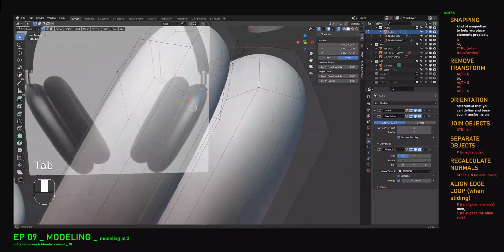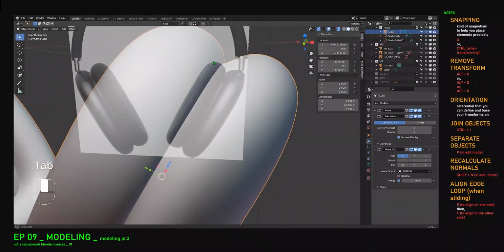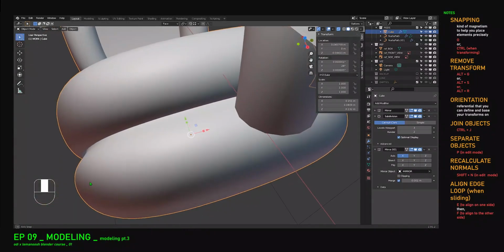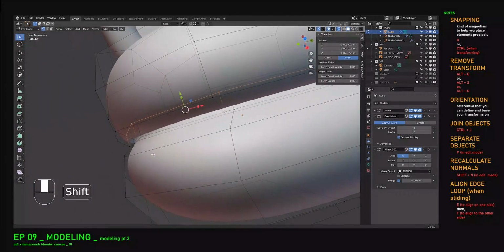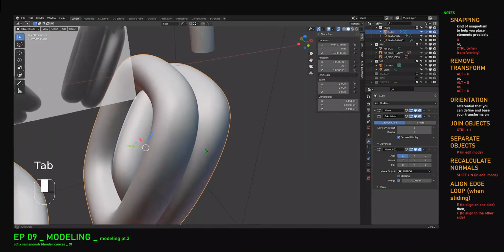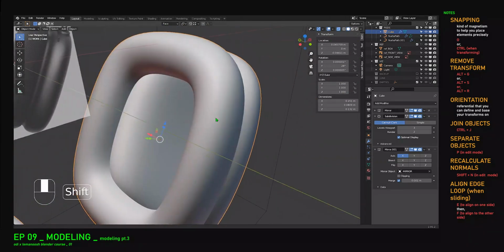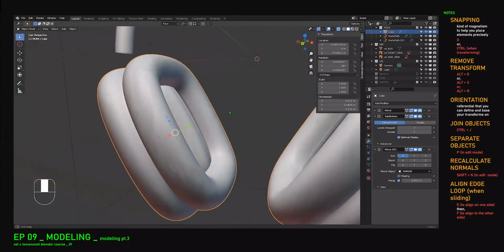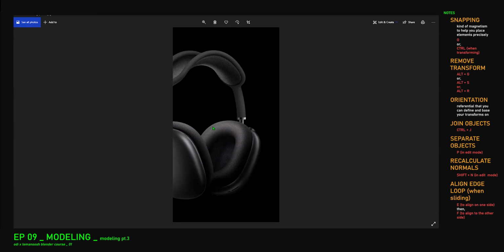So here we just extrude the cushion a bit so that there is a start of a curvature there, and this will help us for the renders. But as you can see here, it's intersecting but not down there, so let's just take those 4 points and let go inside a bit so that it's completely closed. Yeah, nicer. So inside won't be a big challenge, as you can see in the pictures. It's just a super simple cushion, so we'll probably do that later on.